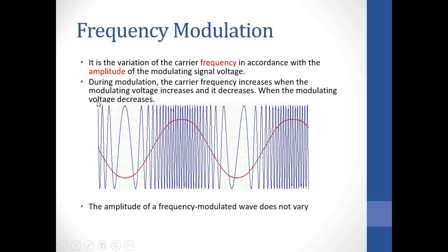The amplitude of the frequency modulated wave remains constant. It doesn't vary, which actually means that the power of this wave is also constant. It's just the same as the power provided by the carrier. Unlike in our conventional AM, where we said that we've got three components: we've got VC, the upper sideband, and the lower sideband, each having a different amplitude component.